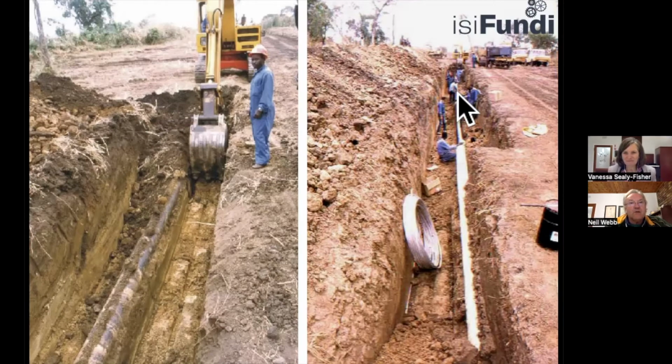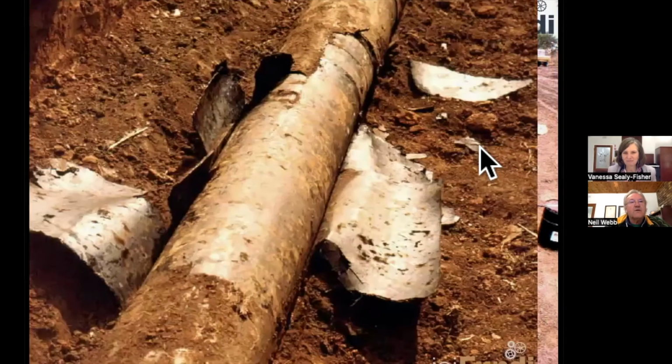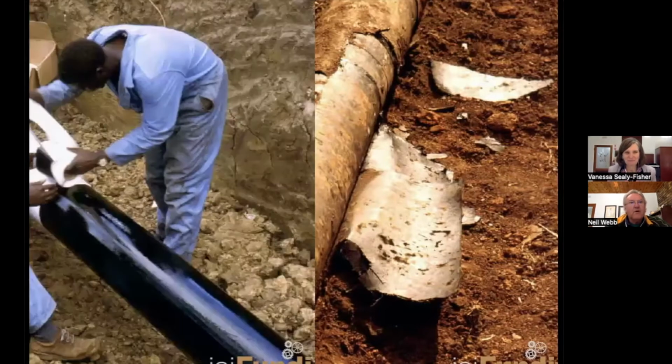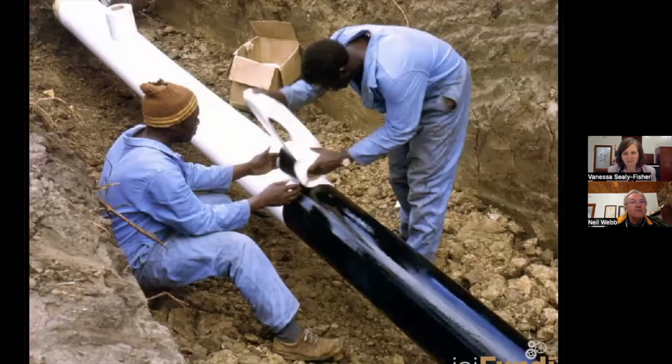And in this photograph, you can also see that guy over there is actually doing some butter welding to weld up a fairly significant pit, an isolated instance. And these sections were then rewrapped for obvious reasons. That wrapping's not doing much good anymore, and the new wrapping was applied by hand. So there was quite extensive repair work undertaken, but did that fix all of the problems, or did you do further studies?